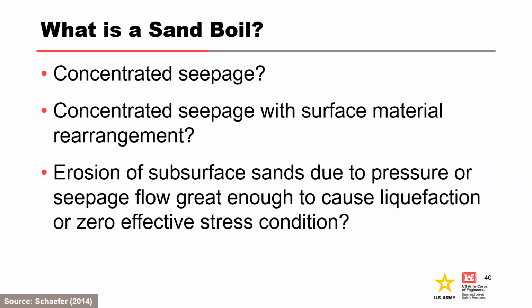What is a sand boil? Some common definitions are shown on this slide. Which one do you think is correct? Sand boils are not concentrated seepage, and they're not concentrated seepage with surface material rearrangement. Sand boils are erosion of subsurface sands due to the pressure or seepage flow being great enough to cause liquefaction or the zero effective stress condition.